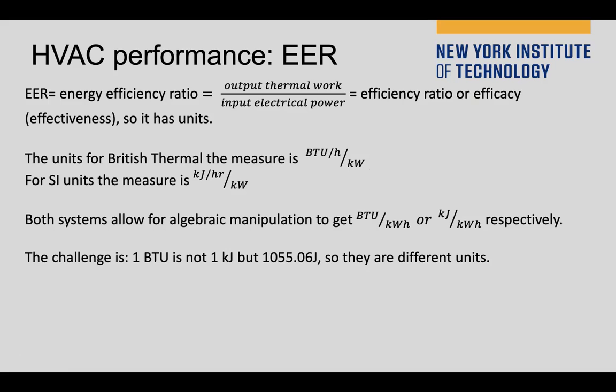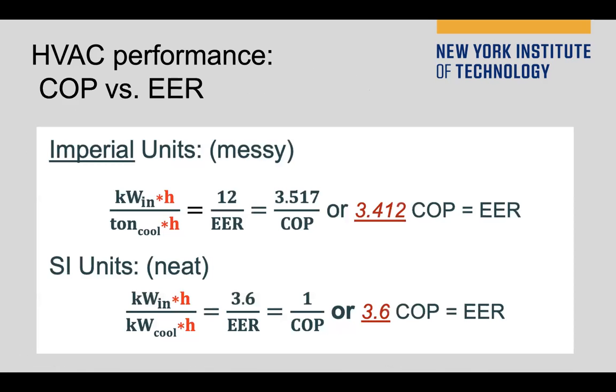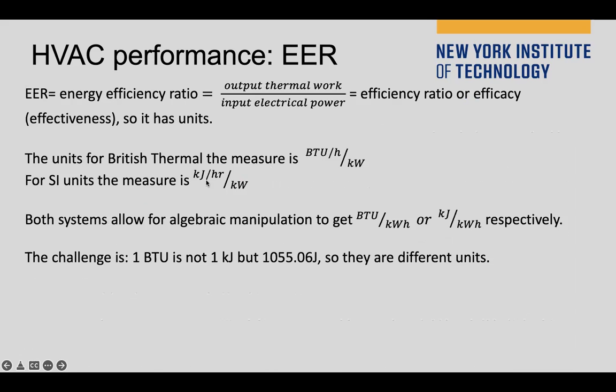Any question on that? No, it's fine. Okay, I skip a little bit. If a question asks you to define the relationship between COP and EER, then you need to know the unit difference on EER. We work it out based on the units and transform EER to COP.